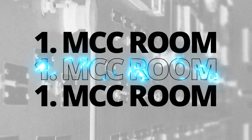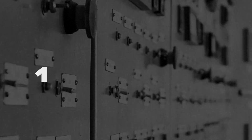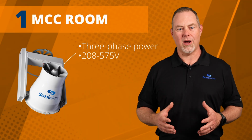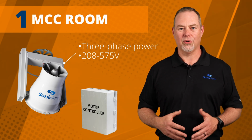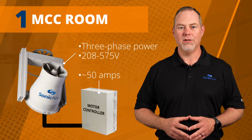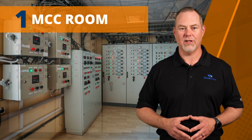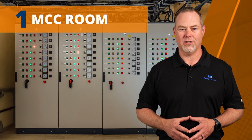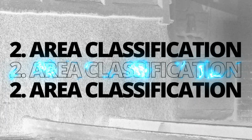First, your motor control center, or MCC room as it's commonly referred to. SonicAire fans run on 3-phase power from 208 to 575 volts, and you'll need a motor controller with approximately 50 amps of power available. You'll also need to let us know where the MCC room is in relation to the area where the fans will be installed. The closer the better.